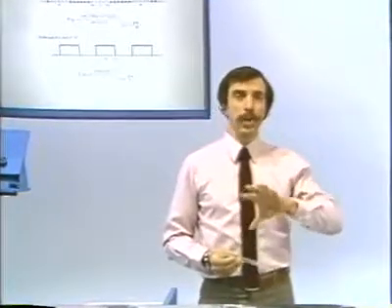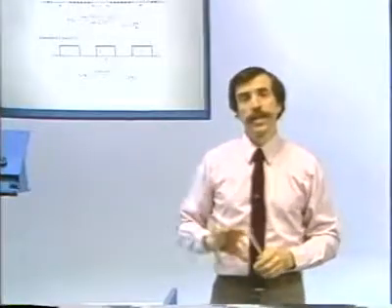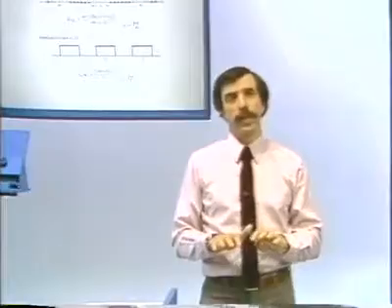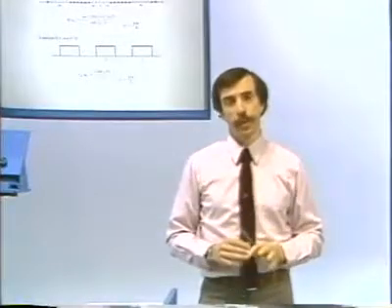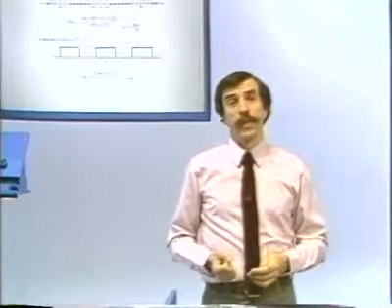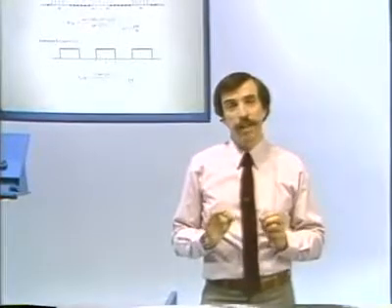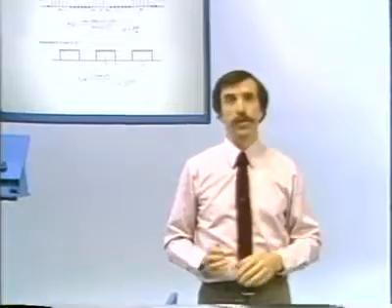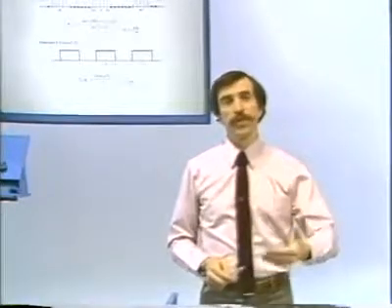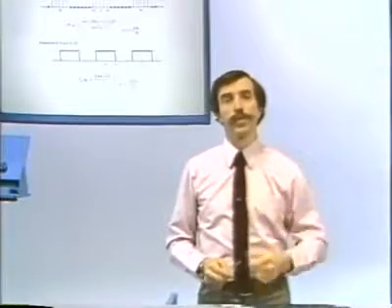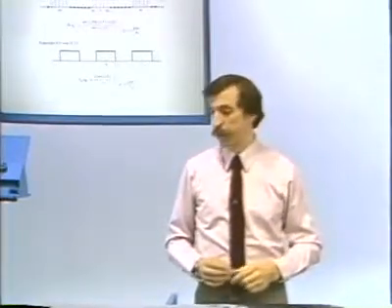In fact, we should understand right from the beginning that the sine x over x envelope couldn't possibly be the envelope of the discrete time Fourier series coefficients. One obvious reason is that it is not periodic. What we require, from the discussion I've just gone through, is periodicity of the coefficients, and consequently also periodicity of the envelope in the discrete time case.